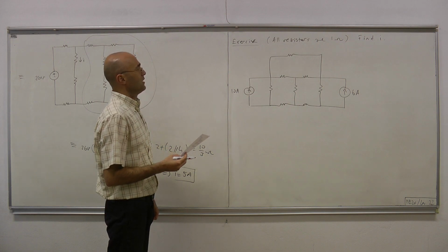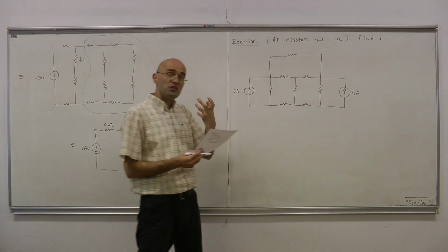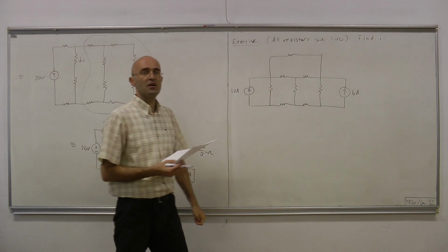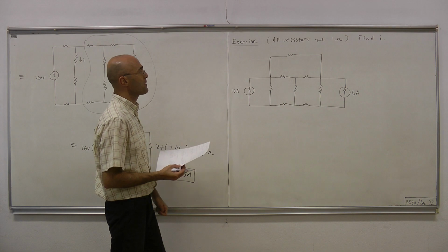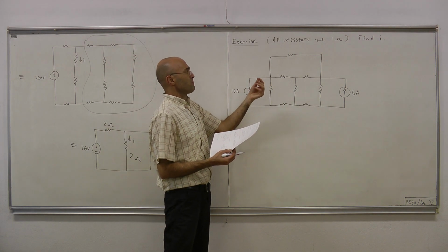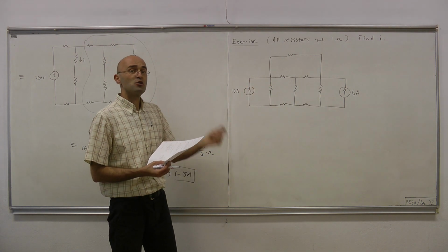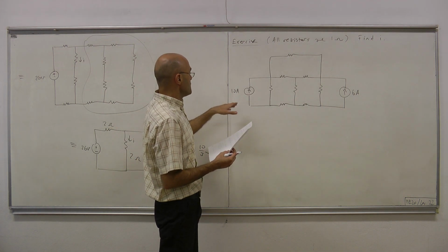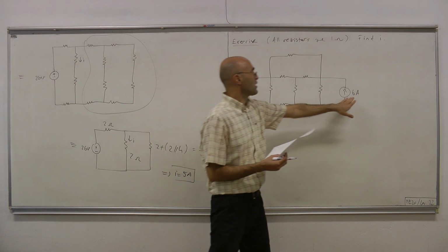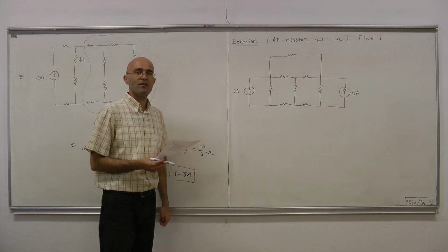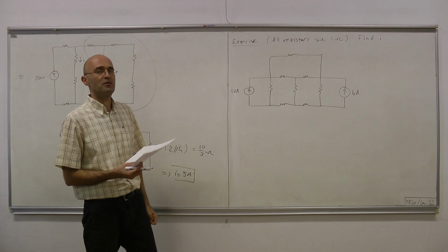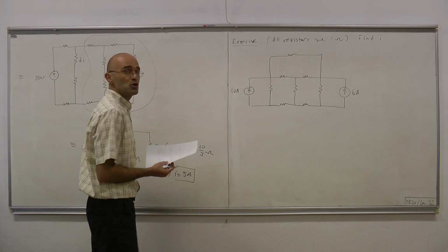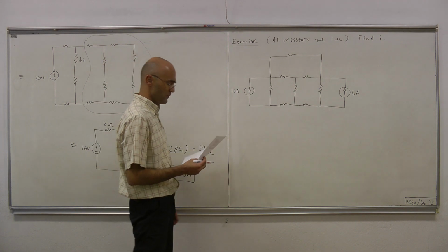Okay. Now, even though the resistor part of the two-port and the fact that we have current sources on either side makes the circuit symmetric, there is one thing that harms the symmetry, and that is the fact that the magnitude of this input and the magnitude of that input are not the same. Therefore, that breaks the symmetry. Okay? But still we have hope, thanks to linearity, and we can go as follows.